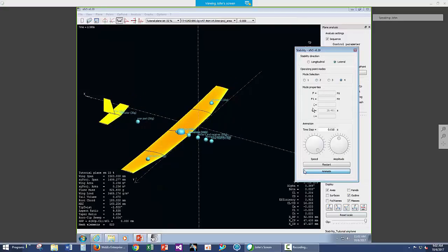And then there's the spiral instability. This is playing. It is a spiral instability. What it's doing is just moving. It's very, very slow. You will have this in your airplane. Pilot automatically corrects for this. It is a killer of people like the Kennedys. Got in a spiral mode because they were in a very low visibility situation. So this is here. You can get the full static and dynamic characteristics if you want.